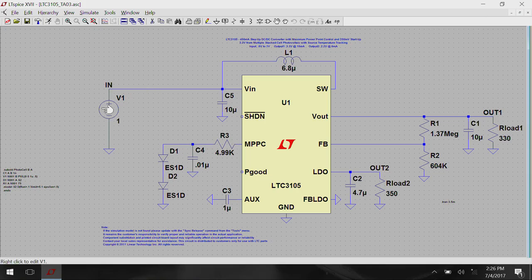Now, this is essentially the solar panel, which is supposed to give you 1.2 volts under very good lighting conditions, and under indoor conditions the open circuit will still give you significant output, but because the lux is poor you cannot draw too much power. Whatever may be the case, this input will never fall below the set point of 700 millivolts. That is the beauty.